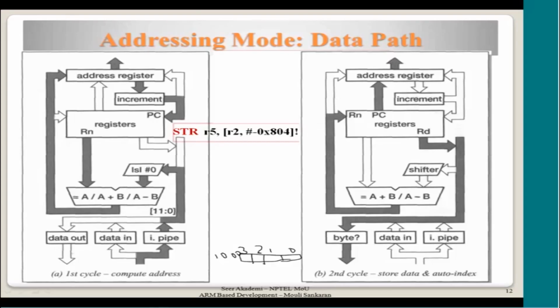So the memory could be... because if you remember, this ARM processor can be integrated with any memory, right? So what is done by this unit is, it will replicate the value in all of the bytes, and then write that value into the memory. Suppose you are writing 5, that 5 is written into each of the bytes.